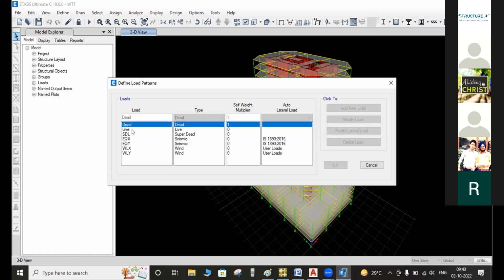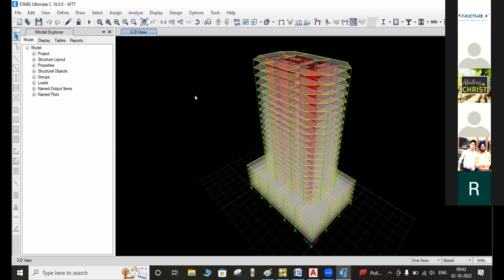Okay, fine. So after putting the load, what will be the next procedure? We have to select the frames, select the beams, and apply the frame loads. Then we move to the area load and the shell part also. We have defined the sets also, like for gravity loads, the bathroom and kitchen portions defined or applied in our model, sir. Okay, so in this way we are applying the gravity loads.